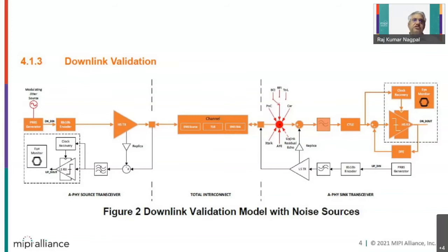Okay, so the static noise sources are like crosstalk. The crosstalk is coming from two sources. One level of crosstalk is coming from your interconnect channel, wherein in an automotive environment you have got a harness in which all the data networks are running, and you have got these coaxial lines running with multiple things bound together to save space.